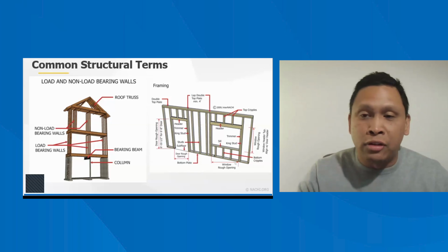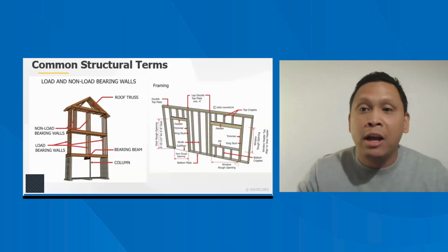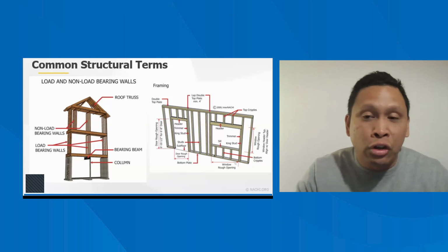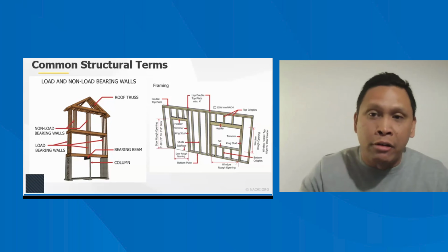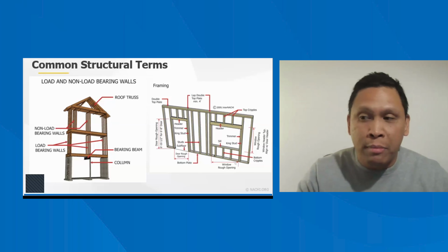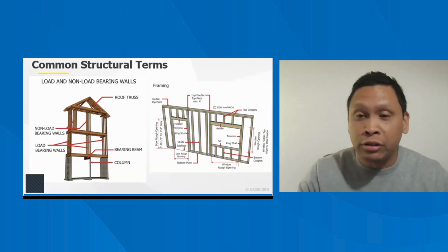And hey, maybe sometimes the squash block system wasn't cut long enough. Maybe they actually didn't secure the squash block system directly underneath the king stud, underneath the window, to the wall and to the framing system. And sometimes you can literally remove the squash block system, which helps support the load from above, right out from its position. Really interesting.